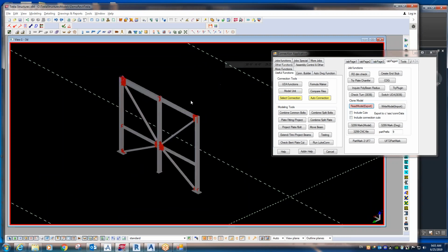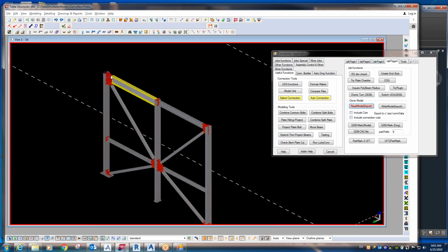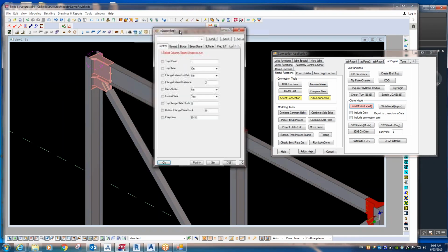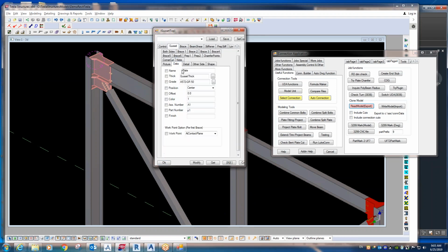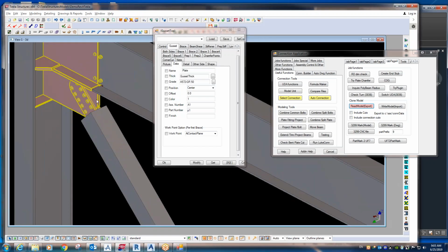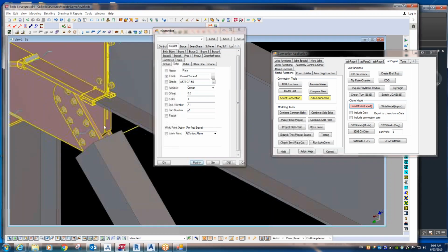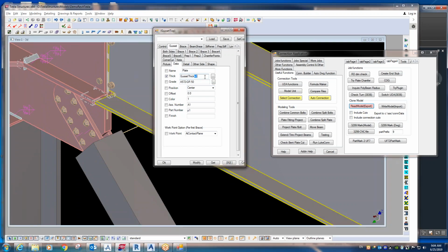Okay. Let's say this is a frame made in Tekla. So you can see all those connections. And actually we are calling this auto connection because we are using a formula reading a table per design. Then you can see the thickness is read from a table. So I can say change, I will add another inch over here. Then you can see the thickness of the gusset increase. So that's the connection.